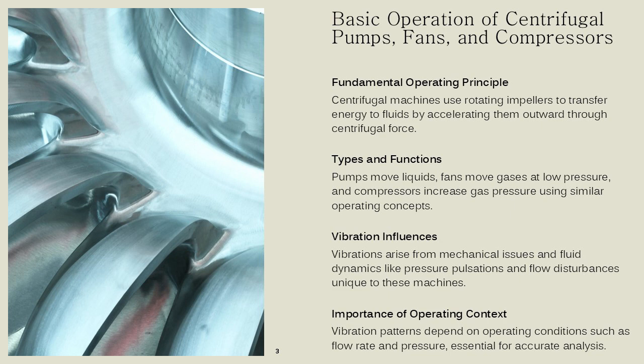From a vibration perspective, these machines are influenced not only by mechanical forces such as unbalance, misalignment, and bearing defects, but also by hydraulic and aerodynamic forces that are unique to fluid handling equipment. Pressure pulsations, flow disturbances, and interaction between rotating and stationary components create characteristic vibration signatures.